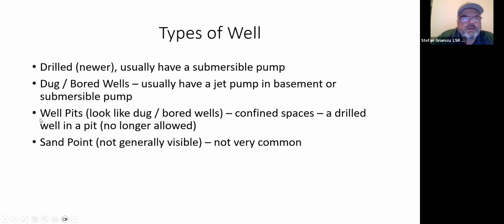Well pits, these are kind of an older style of drilled wells. They actually are drilled wells, but they're in a pit. So they look exactly like a dug or a bored well, unless you open up the lid and you'll see the drilled well inside. So I'll show you a picture of these. They are not allowed anymore. They're confined spaces, but like anything older, grandfathered, we don't have to replace them. But I do like to explain to people that they're confined spaces. So definitely need to follow a certain procedure when we're working in a well pit.